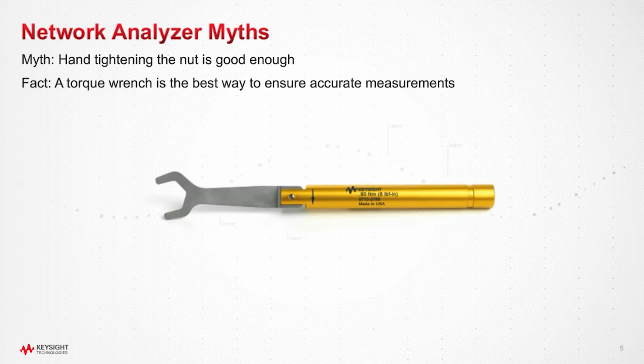While hand tightening can be adequate for a quick and dirty spot check, if you really want measurements that you can rely on, you're going to have to use a torque wrench. Torque wrenches come in different strengths depending on the type of connector you're using. So make sure that you're getting an adequate connector contact by using the right torque wrench for your application.